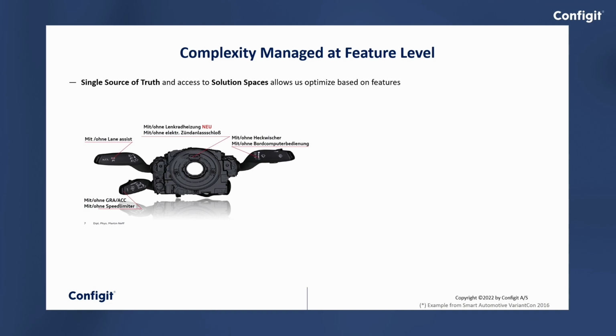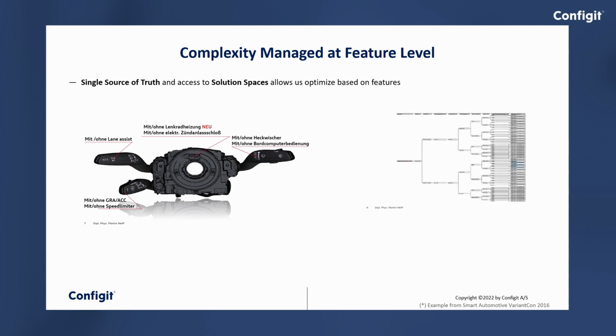And now using the solution space export that we have in ACE, you can build up a tree of all the possible combinations of those controls, those features that control this particular part. And then you can add, and you cannot read the thing on the right there, sorry, too small, but the point is you can then add probabilities of customers making those choices. And what you then can calculate is the probability of each of those variants of this particular part.